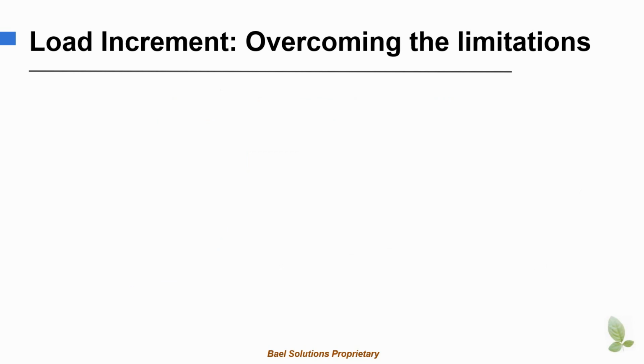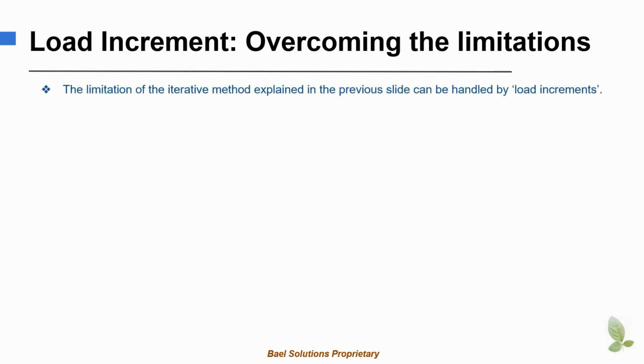We saw in the last slide that in case of a highly nonlinear structure, Newton Raphson iterations may not solve the problem. Now, we are going to see how we can overcome this limitation. The limitation of the Newton Raphson iterative method can be overcome by load increments.